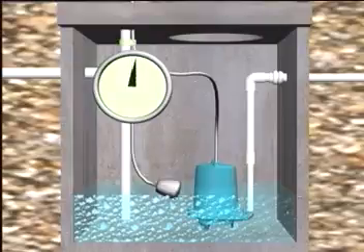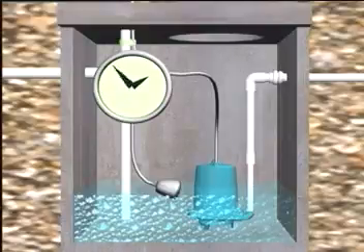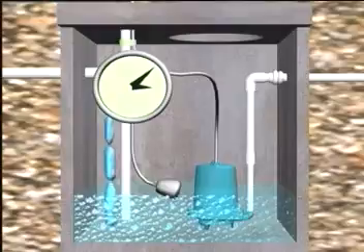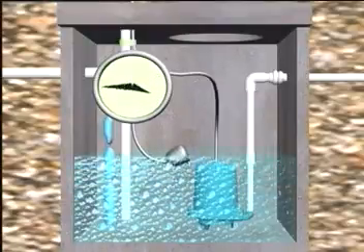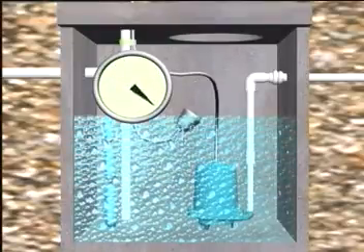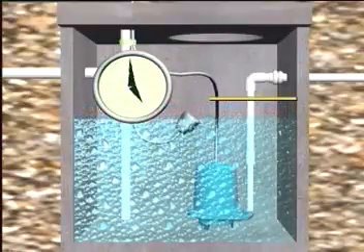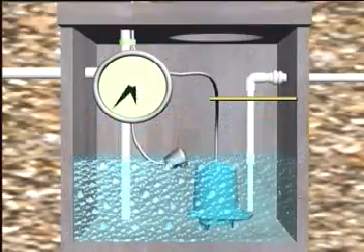In a timed cycle control system, a timer is used to determine the amount and number of times a pump runs to pump a predetermined amount of effluent. A low-level cutout float will allow the timer to start the pump only if there is enough fluid in the tank to allow for satisfactory distribution throughout the absorption field.